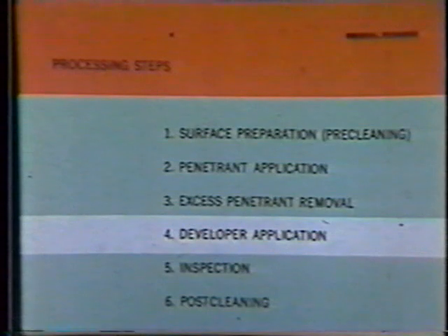Next comes developer application. Water-based developers are applied immediately following the rinse. Dry and non-aqueous wet developers are applied only after the specimen is dried. Best results are obtained with a thin and even coating. No pools of wet developer or accumulations of powder.